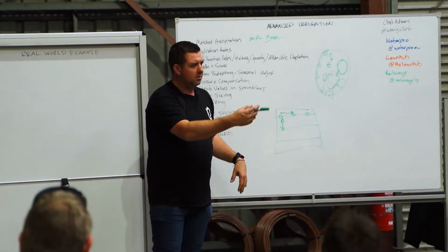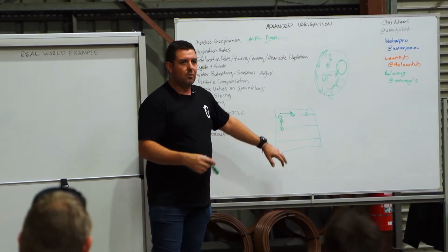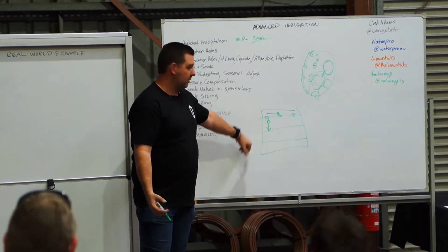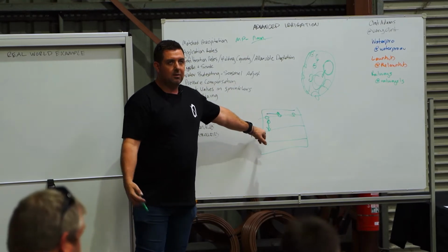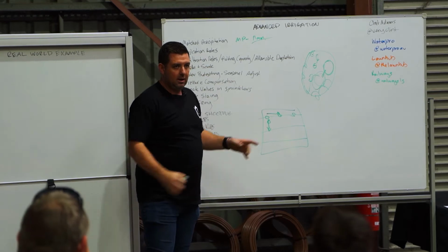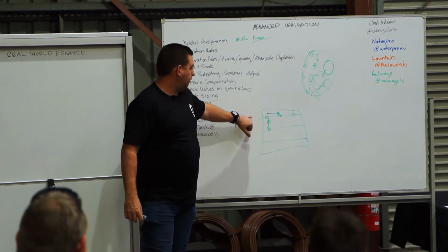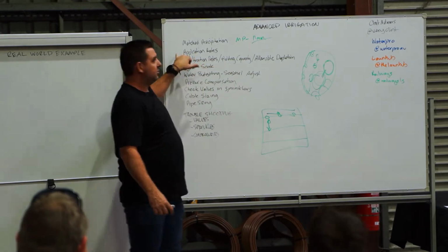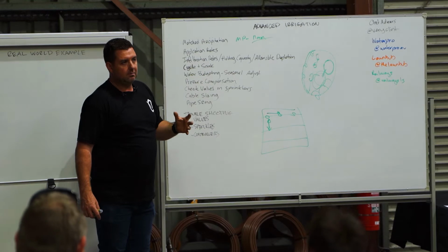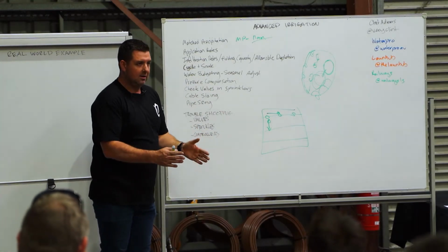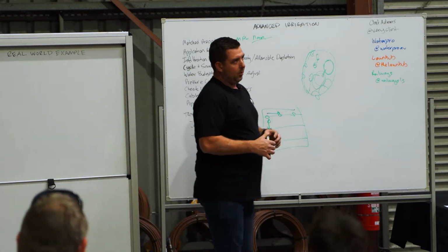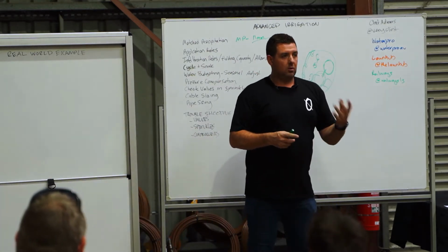Residentially it's probably going to be left in the hands of you to make the right decisions around this. Now, recently, there's a council north of here that had specifications of 0.3, 0.3 and 1.6 litres an hour. The actual application rate or precipitation is somewhere in the vicinity of 25 or 30 mil an hour when you're getting that close together. And you get to a situation where the soil can't actually handle that much water.